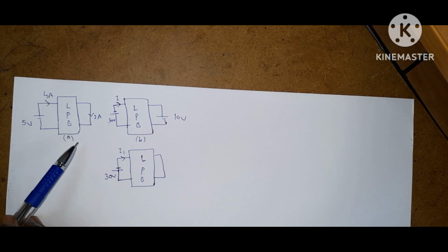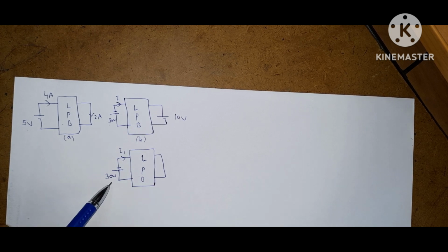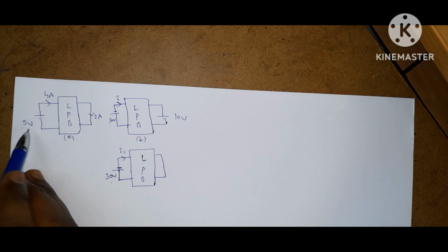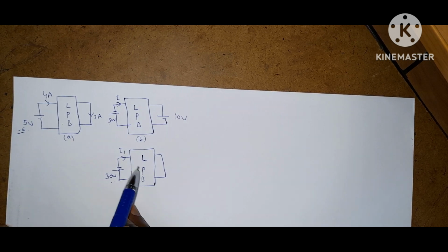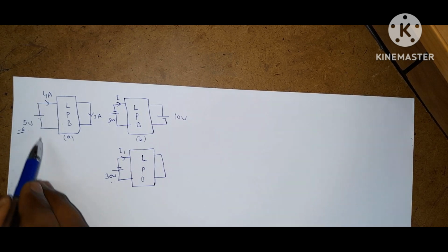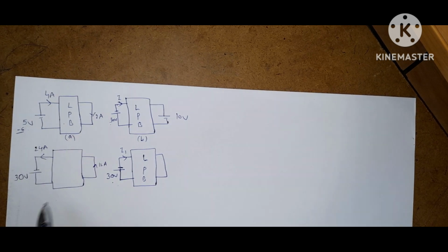If you observe these two circuits, they are almost the same, but the values are not the same. So to get 30 volts and reverse direction, what is the multiplying constant? Here if you multiply with minus 6, then you will get the same circuit. Now if you multiply this circuit with minus 6, all responses and excitation become like this.